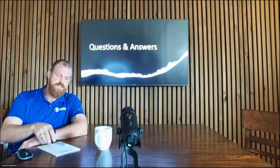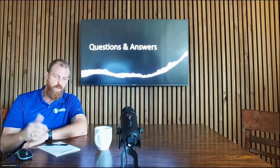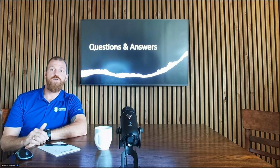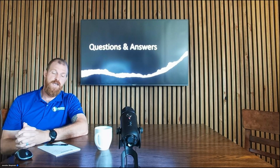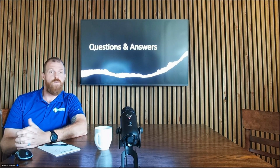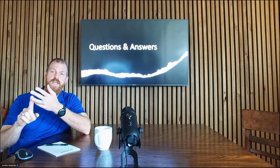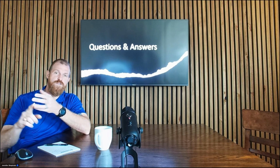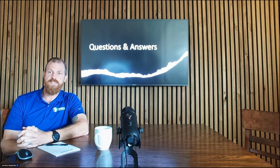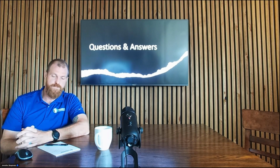So, guys, a couple things that came up during this discussion is, of course, when to switch from annular flow to tubing flow. Biggest question that we see, a very important question. My general response to that is when we begin to see instability, especially instability so bad that it begins to affect facilities, affect compression, even possibly like ESD our wells based off of that pressure swing. Best idea to switch. So from large flow area down to a smaller flow area.